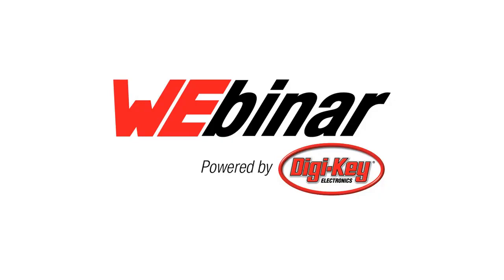When it comes to the data side and the on-the-go, where the source and the sink devices are negotiating, more on the data side, I believe, exchanging device IDs and things like that, that's all going to happen outside of our device itself. There'll be a data controller running in parallel with our power delivery controller. I believe the OTG would more involve the data controller side, and typically that's integrated into the microcontroller or an applications processor. So the 4500 is really just involved with negotiating the power delivery contract between the source and the sink.